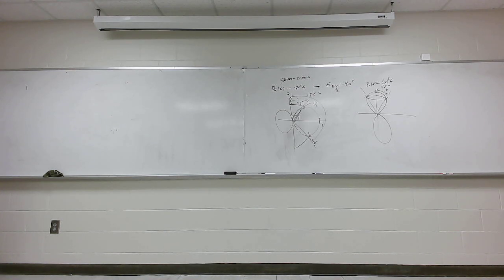Now what happens is they have to solder coax line into things. A half inch diameter solder ball is a giant inductor, and it was at a 1.4 gigahertz frequency. So he goes, do I have your permission to get rid of that thing? Yeah. He was an engineer. He really was. Got rid of it and it worked seamless. But that's my story about don't assume your design was built to spec and works if you can't be there. This is personal to me because I thought I was going to lose a lot of money.